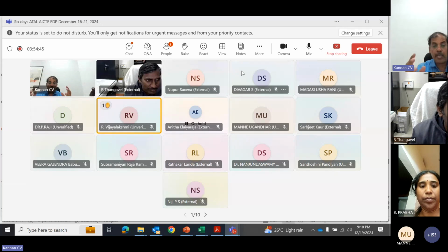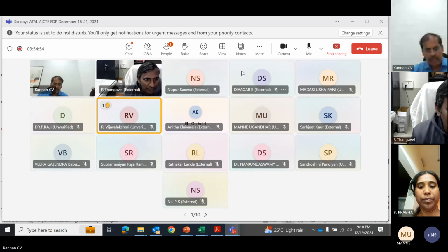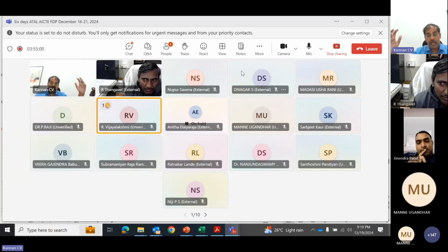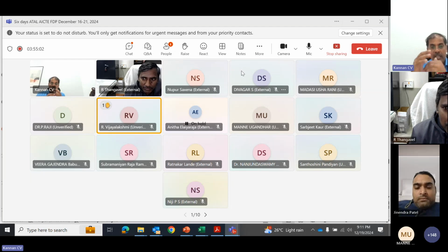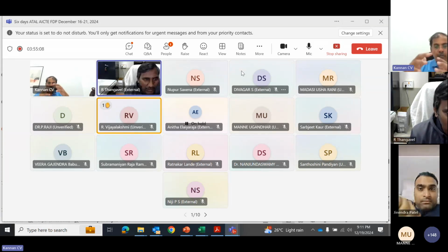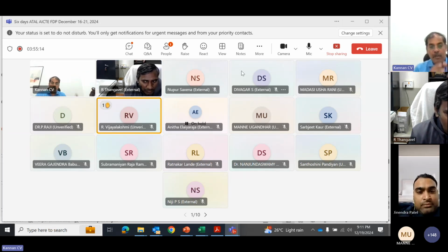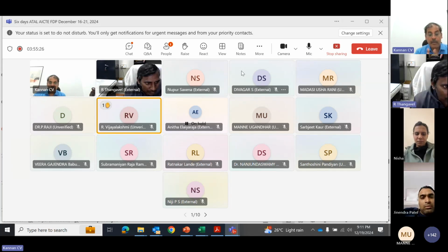So commercially, the product has to be commercially viable. P-type products are more viable than N-type products because of the manufacturing cost. Now again, because N-type wafers have better potential in terms of efficiency, whereas with P-type you cannot increase the efficiency beyond a certain level, right? Now for the economics of N-type, if you have higher efficiency, the power generation will be more, and in wafer manufacturing processes a lot of developments have happened. All these things put together, now industry is moving from N-type to P-type. Sorry, P-type to N-type. Sorry.